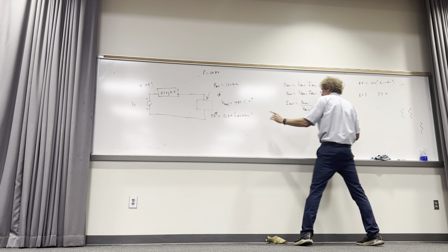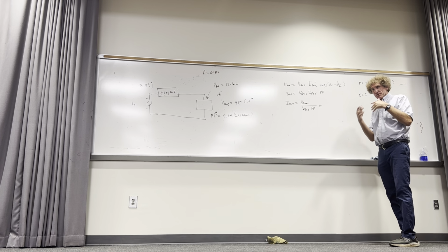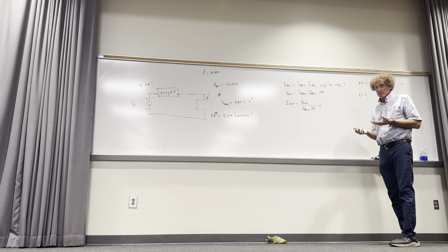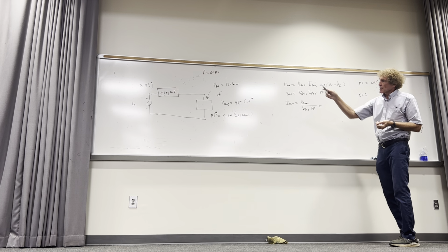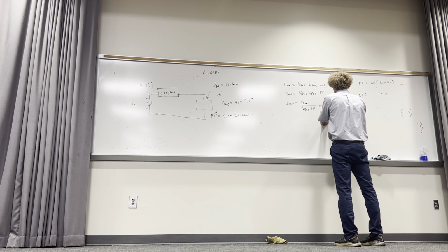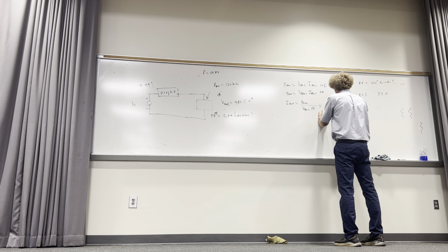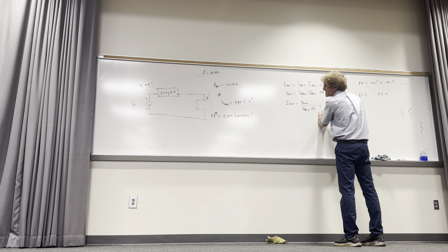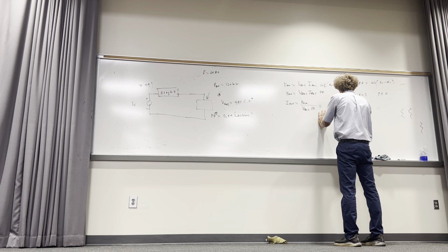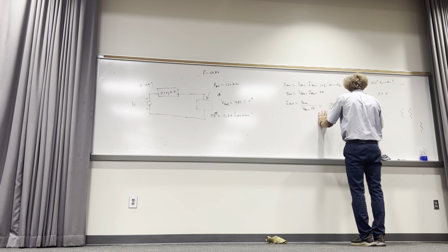Now for this one, I'm not trying to go fast, I'm just trying to make you see this obvious. It's fairly obvious if you've done it. Here we got 120 kW, so it's 120 times 10 to the third, divided by 480, that's the magnitude of the voltage, and the power factor is 0.84. So now we have the magnitude of the current.